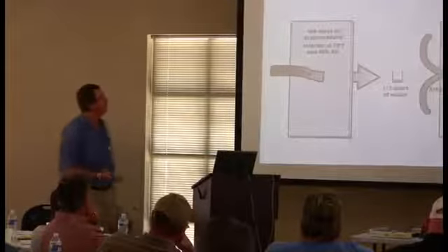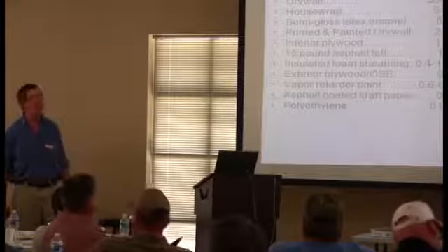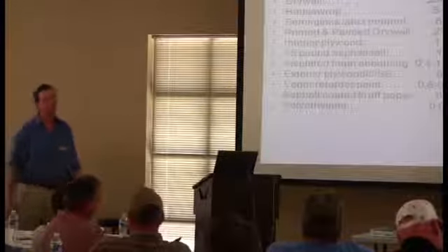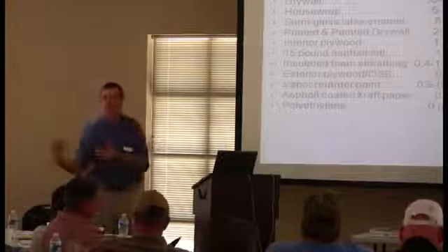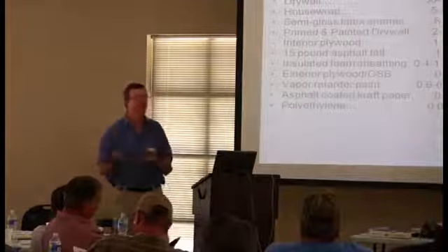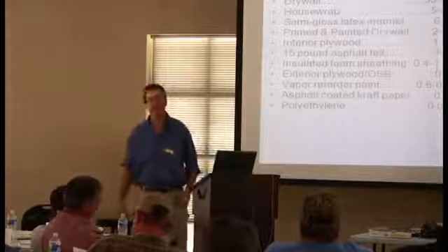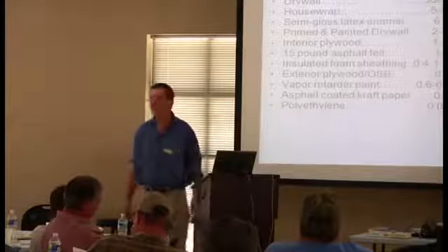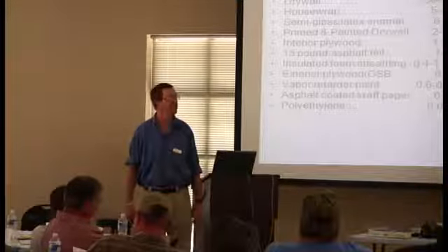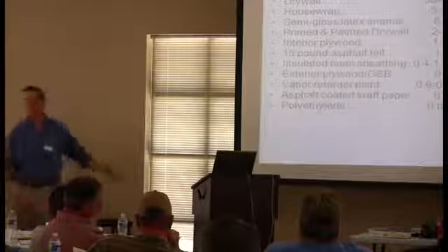Okay. So don't do that. This is a person that put plastic on the inside of their wall, and they had a moisture issue. The wall was unable to dry to the inside. In the summertime, the wall is drying to the inside. In the wintertime, the wall is drying to the outside. They stopped it from drying to the inside. It didn't take long for it to get really wet, start growing stuff, and then attract termites as well. Okay? So stay away from plastic.